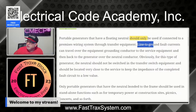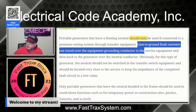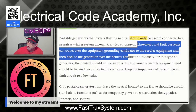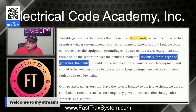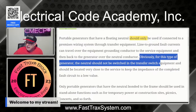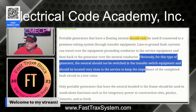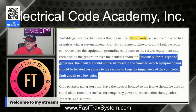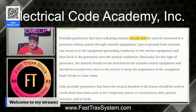Okay, so line to ground fault currents can travel over the equipment grounding conductor to the service equipment and then back to the generator through the neutral conductor. Obviously, for this type of generator, the neutral should not be switched in the transfer switch equipment and should be located very close to the service to keep the impedance of the completed fault circuit to a low value. Okay, so all proximity taken into consideration where you put this equipment.